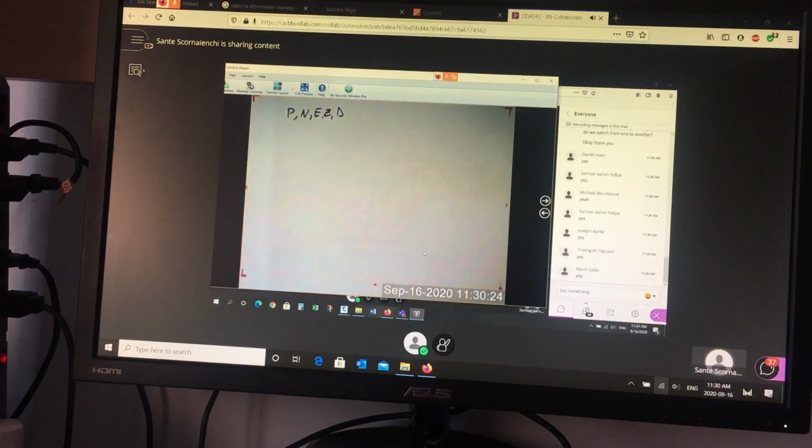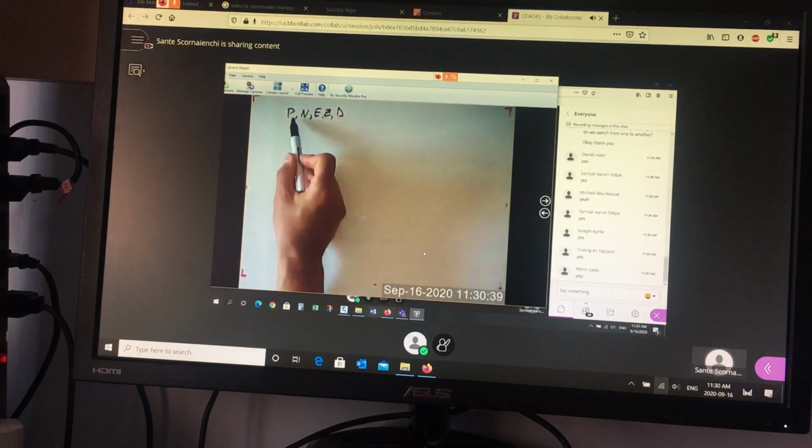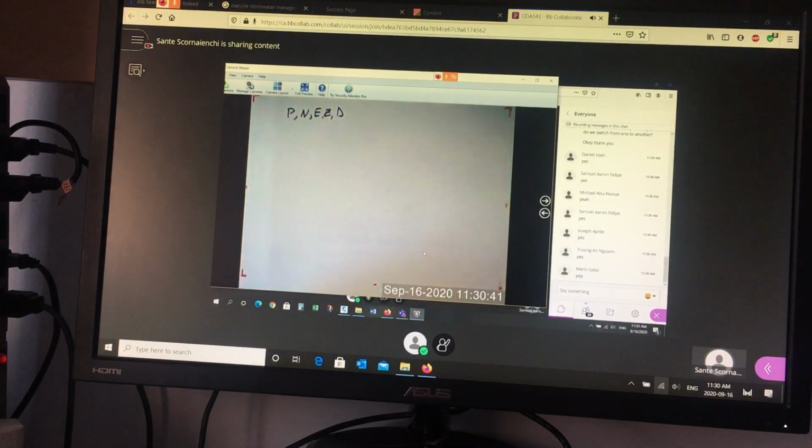So Civil 3D does have a GIS database working in the background, and you'll see it when you create the point data and surfaces and so on. But when it comes to points, it's a kind of a classic thing. A lot of software that uses points uses a similar kind of setup. So for the point data, point number, northing, easting, elevation, description, we want to bring in the point object. So it's the graphical representation of the point.